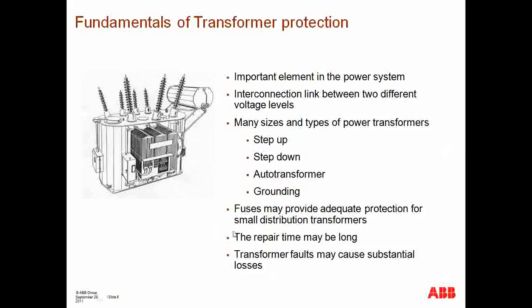A couple of points here: again, repairs take a long time, and also given the size and the transportation cost and limitations, it's not easy to replace a transformer. So there's a lot of considerations on that front. That's why not only the protection, but the monitoring of the transformer is important, to ensure that it is running properly, and we don't have a run-to-failure type of scenario.